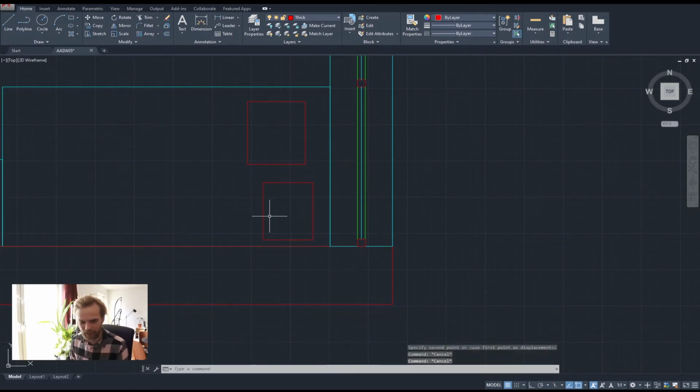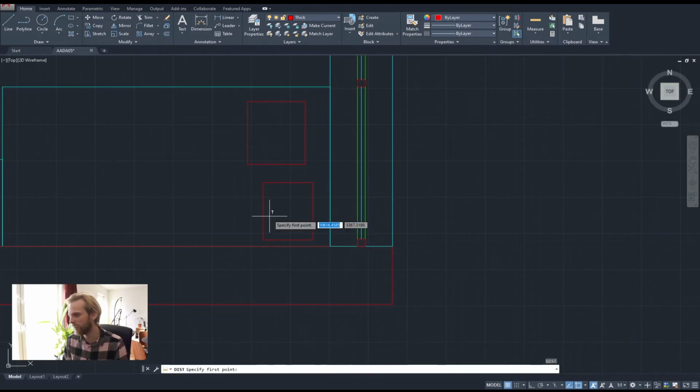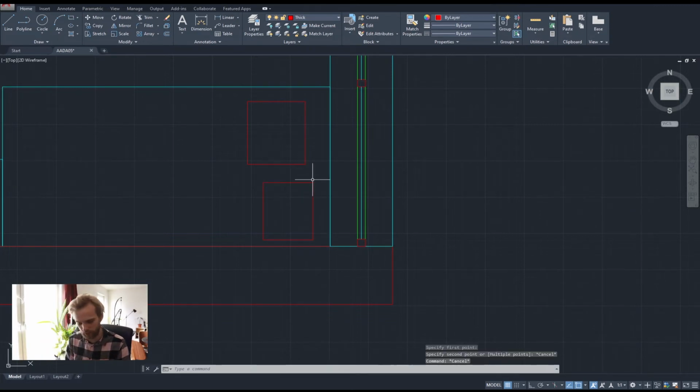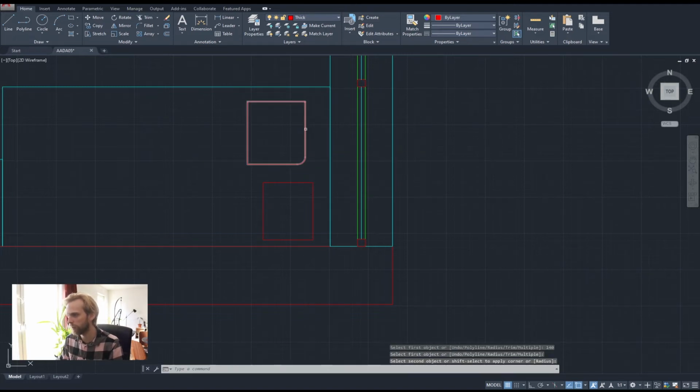Pillows are not that accurate, so I can get away with making weird ones. Just for reference, I'll measure the distance. That's 300 millimeters. So I will fillet all of the pillows by 130 or 140 millimeters, right? So all of the corners get filleted.